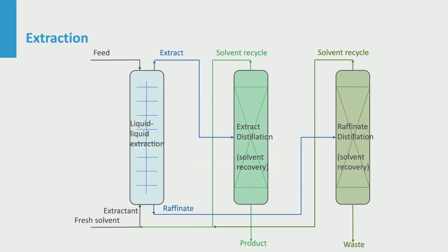As mentioned before, extraction should be done using multi-stage countercurrent contact. For liquids, this can be achieved in extraction columns. Raffinate is feed depleted of product. Raffinate has become saturated by the extractant, leading to a new separation challenge. The solvent for an industrial extraction must meet many requirements, sometimes too many. Solvent losses may have to be kept far below 1%. That can lead to distillations of both phases that leave the extraction column, so a lot of extra costs. This picture shows an example.